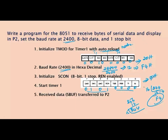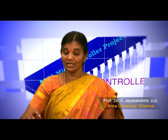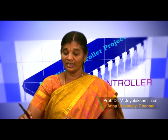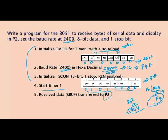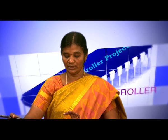Okay. Then after initializing these 3, now you can start the timer. Start the timer. After starting, what will happen? The data will be received and stored in the buffer. In SBUF only it will be stored, then we have to use the instruction to move to P2. Once it is P2, physically you have to make LED connections from all the pins of P2. In the breadboard you can make the connections, 8 pins with the 8 LEDs. After executing the program, automatically the received bits will be displayed on your LEDs.